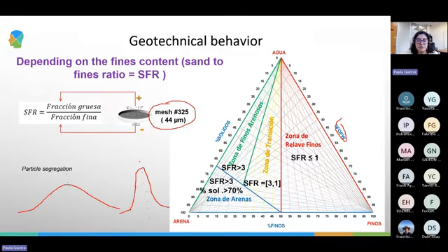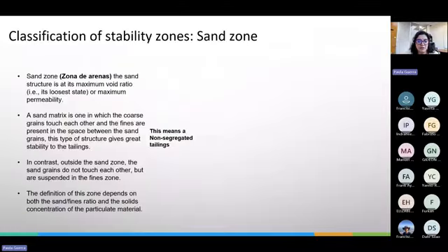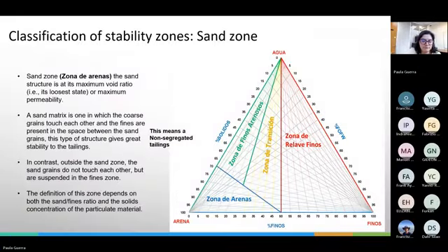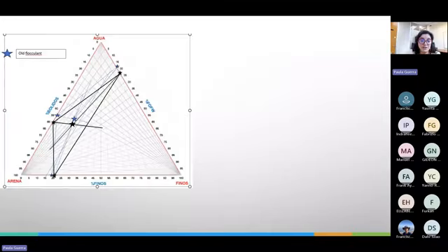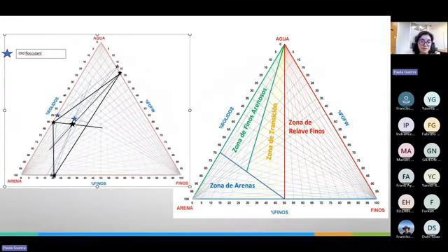So maybe in terms of improving settling conditions or stability, they're both very much equivalent, but the second choice, the use of new coagulants, since we're talking about a higher percentage of solids, might be a good choice, okay, because it does allow the recovery of an additional amount of water. Okay, remember, the more the solids that you have, the more water that you will be able to recover, okay?